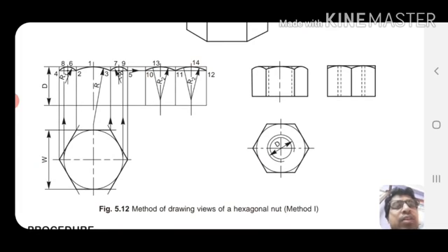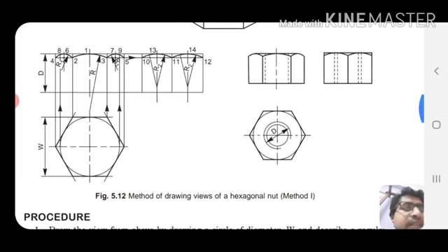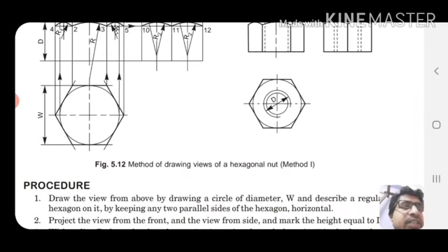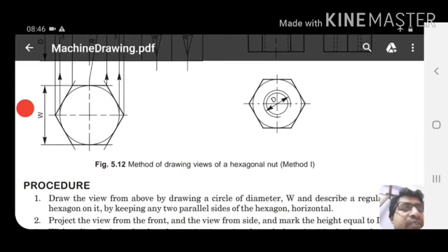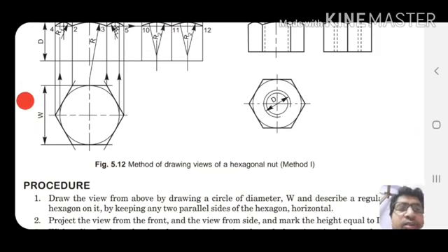Okay, so this is the top. This is the front, top, and another one is the side. Front view, side view, and top view. Top view is below. And very interesting, there is a 3/4 circle. The 3/4 circle indicates one is the D diameter, another one is the 0.85 D core diameter, and the 3/4 circle is the outer one. That indicates the thread should be the inner one. Okay, 3/4 circle outer one, that indicates, according to the drawing language, that the thread is the outer one.